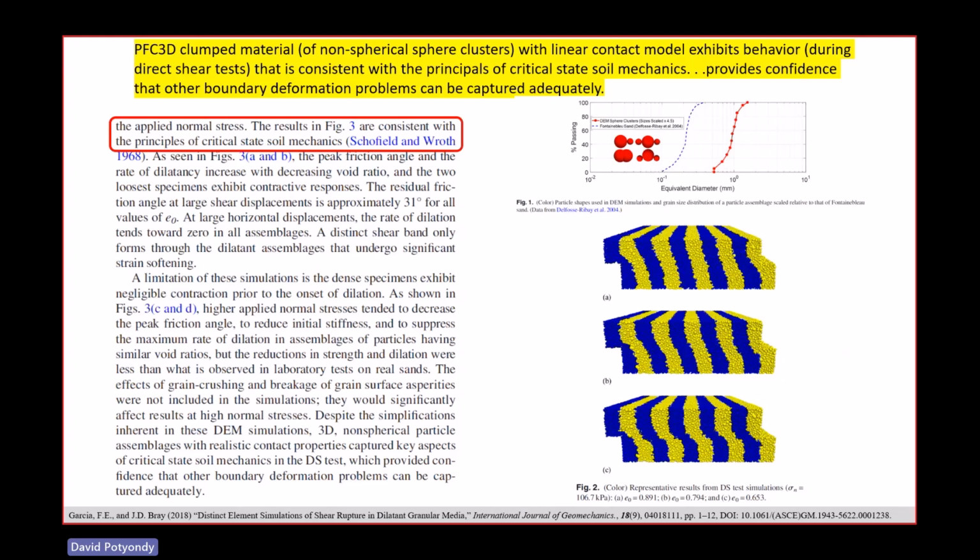And then in addition, they matched the size distribution of a particular type of sand, Fontainebleau sandstone. Notice the thing I always talk about. This is the real sandstone size distribution. Notice the length scale, 10 to the minus 1 meters, diameter grains. What they did is shifted everything over. So their system has much bigger grains, and boom, they cut off the small ones. It's what everybody does. And so then they did shear box tests.